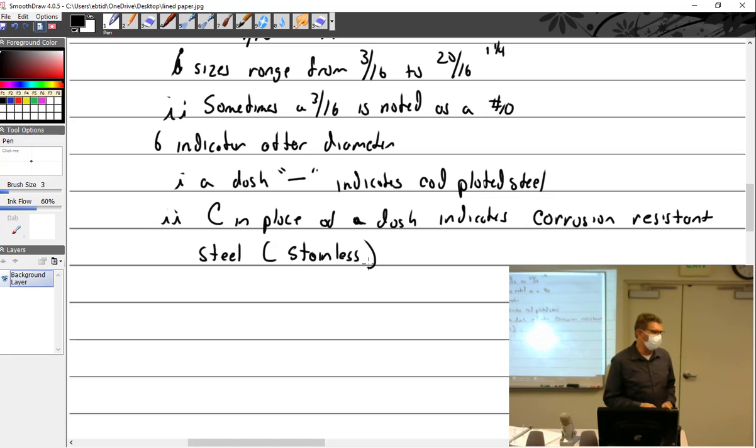I took this cool welding class, and the instructor said there's two: austenitic and martensitic. The martensitic, M, is magnetic. The austenitic was not magnetic. But it was kind of cool because he got a piece of austenitic red hot, stuck a magnet to it, and lifted it up. Then it cooled and fell off the magnet. So that's a whole other thing.